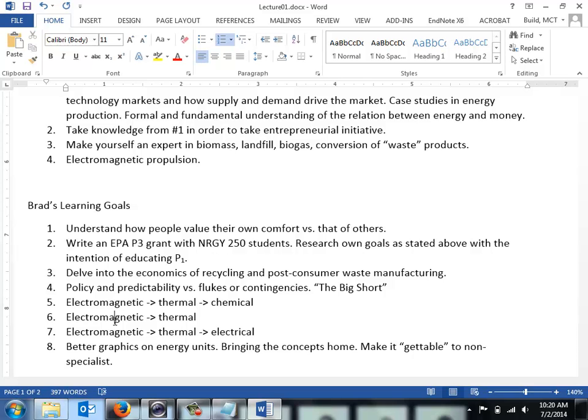But he used a polystyrene insulation, which has a melting temperature somewhere around 110 Celsius, maybe 220 Fahrenheit. So when his manifold was hitting 240, 250 Fahrenheit, he was melting this plastic. So, yeah, then we're all kind of like, whew, yeah, let's do it. Who broke out the modeling glue?